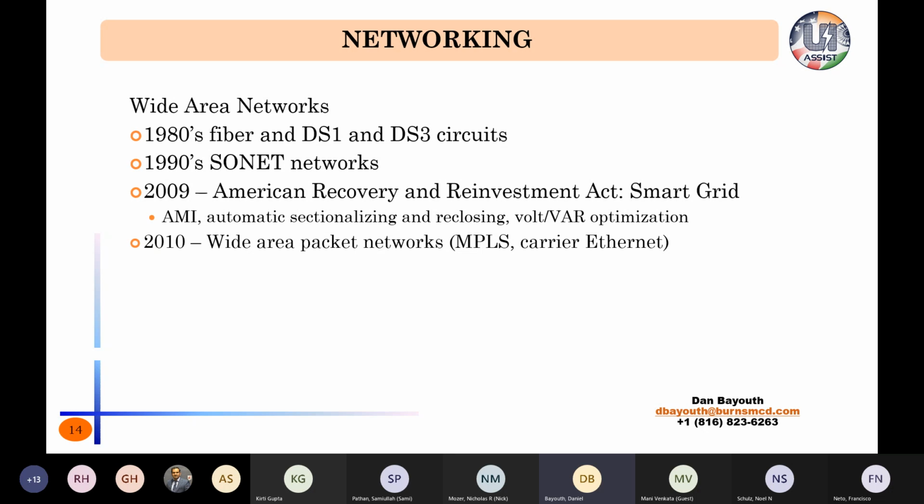So in the 1990s, we start to see high speed, at the time very high speed, 100+ megabit private fiber optic networks they could start running. So in the 90s, it was, well, we have all this fiber, and adding a network on top of that is an incremental cost, but we can also converge all of our applications onto a common infrastructure. And in the 1990s, a lot of this was serial traffic, like RS-232 serial, a lot of 2 and 4 wire voice frequency circuits, and some DS1s for the land mobile radio system. But these were the kind of things we saw on the SONET networks, and they all fit together very well.